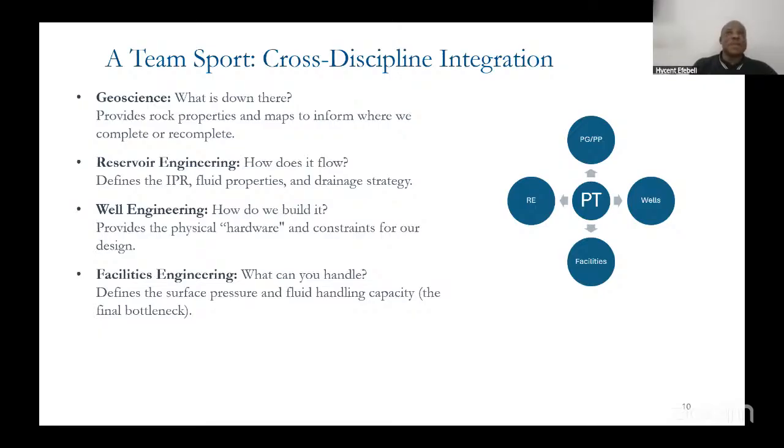You see the PP looking at fluid contacts, the wells that produced around there, and when we last acquired a saturation log. What is the current oil water contact? He is looking at all those so that we don't perforate into water. Even when we are perforating, he is also in the field, making sure that we do proper correlation and that we don't perforate at wrong intervals. So they contribute a lot.